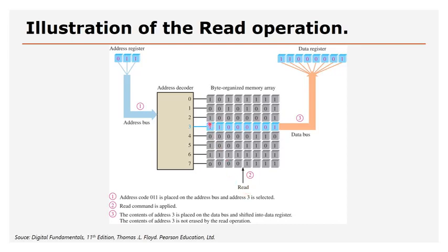What's basically going to happen is this blue register will be placed on the data bus. It says data register, and this will go out to the data bus in any case. So if you can see 11, all zeros and another one, that's the data that was read and placed on the data bus. This was the address, number 3, and the information there is placed on the data bus. As I've said, this could be a read from a RAM device or a ROM device.